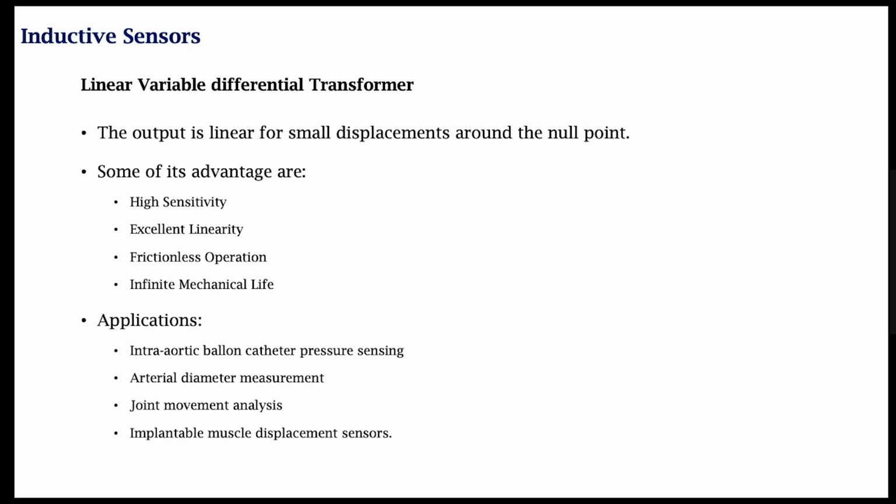What is happening is only magnetic inductance or magnetic coupling, but there will be zero electrical contact. Now that ensures that there is no electrical wear, so there is no mechanical wear, because this is happening in a frictionless environment in a captive core with the hermetic sealing, and there is no electrical wear because there is no electrical contact with the coil, for example.